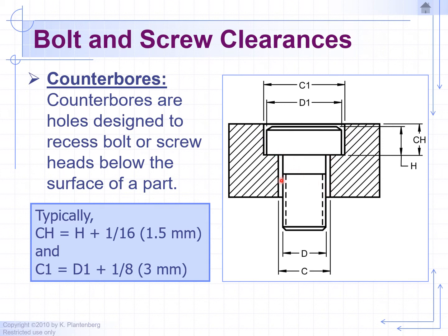That's where you drill a small diameter hole into a block, and then you come in and drill a larger diameter hole. That's referred to as a counterbore hole. And 99% of the time it's to accommodate a bolt and to hide the head of the bolt. So in some cases, like in the previous slide, if you don't want the head sticking out because maybe something may be on top sliding back and forth, or you don't want it to get in the way of some other operation, then one thing you can do is hide the head of the bolt by drilling a counterbore hole.